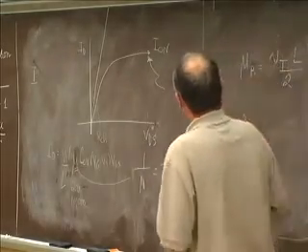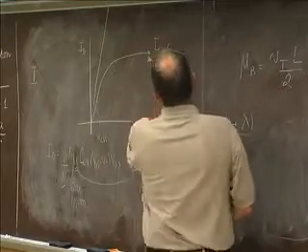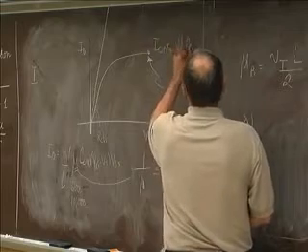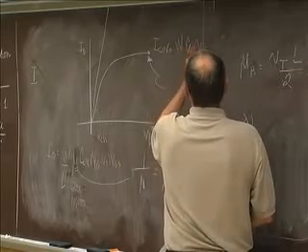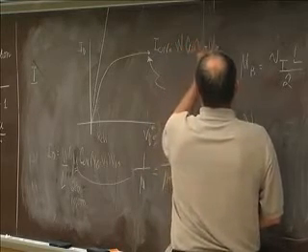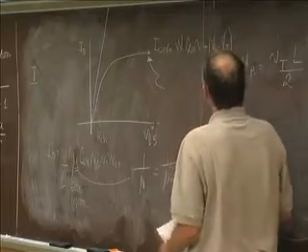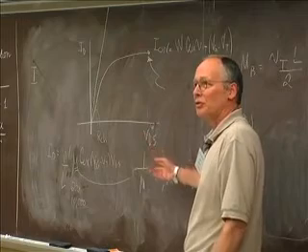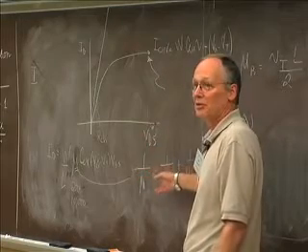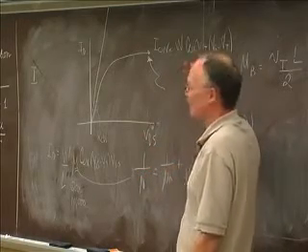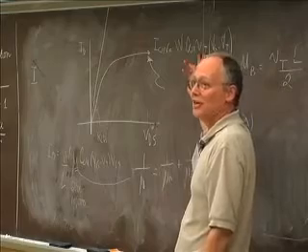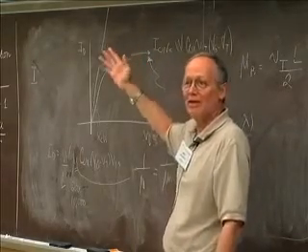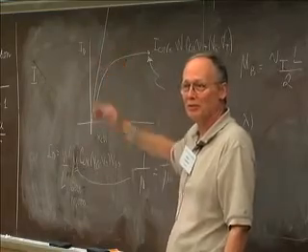That thermal velocity, remember what the on current was. It was W times Cox times the ballistic injection velocity times Vg minus Vt. So what's giving me the high mobility, part of it is due to low scattering, part of it is due to light effective mass. The light effective mass is also giving me a high injection velocity. So that's boosting my on current. That's good. I'll have a higher ballistic limit in those materials.